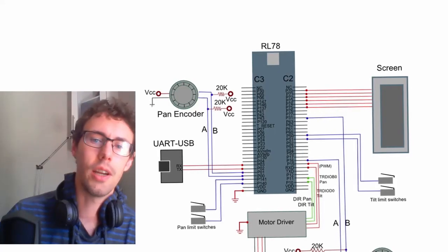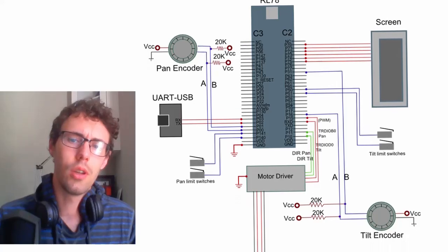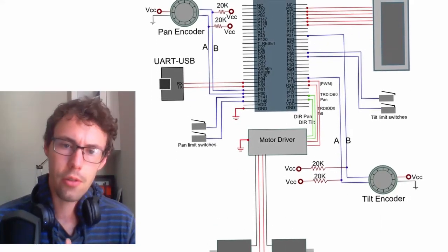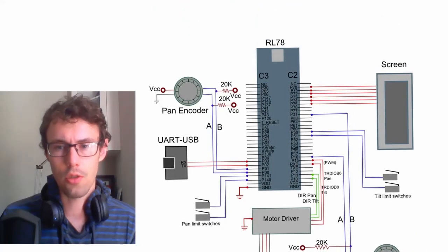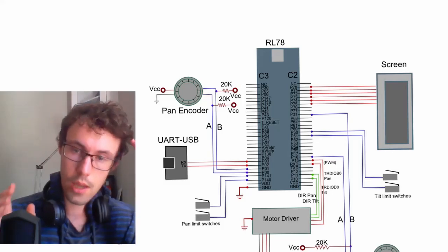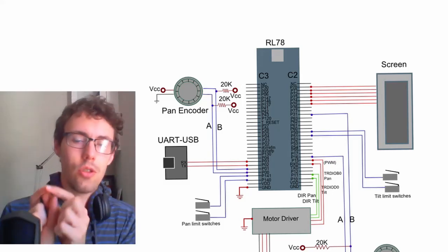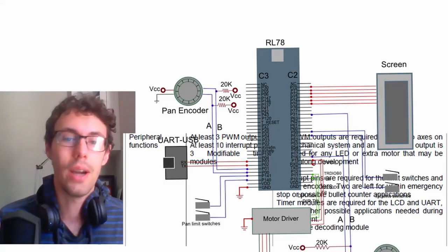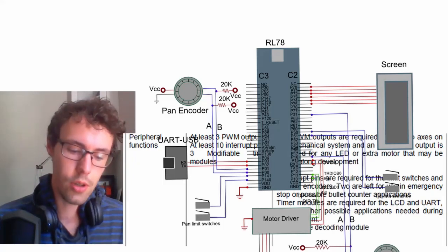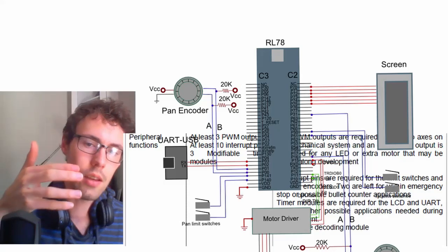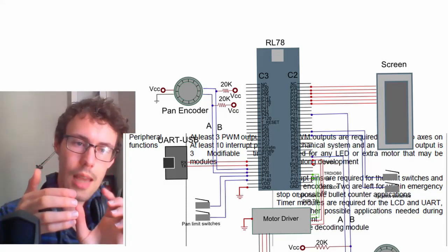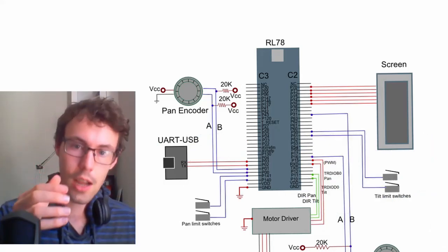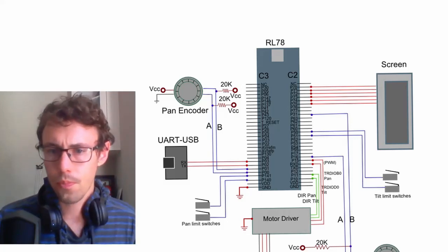This is a pinout diagram, so you then want to figure out which pins of the microcontroller can do which things. An MCU has dedicated circuits for certain things, so sometimes you don't even need to write code to read an encoder. You can literally just hook up the right pins, and they have some built-in circuitry that outputs the number of counts of the controller for you.